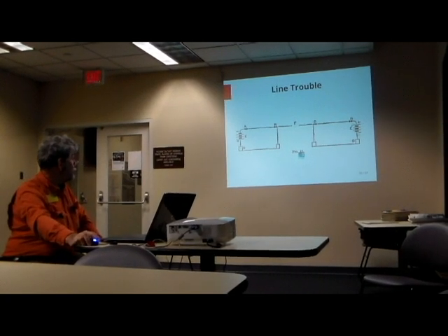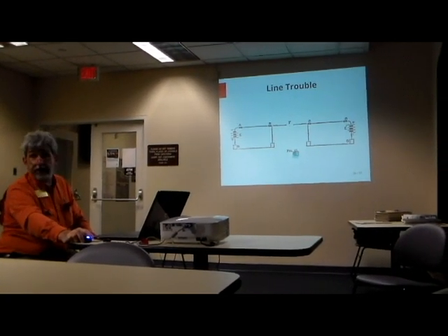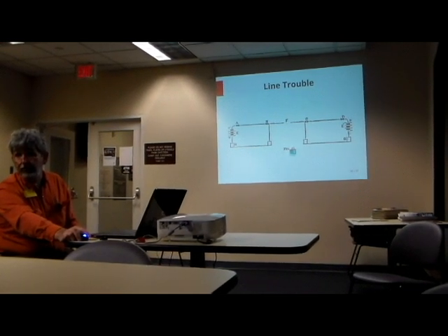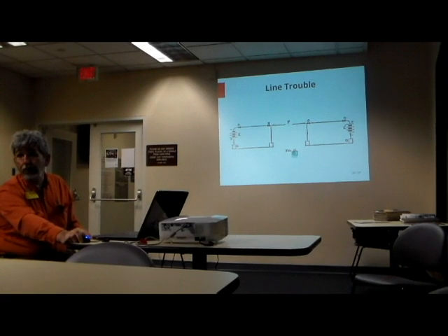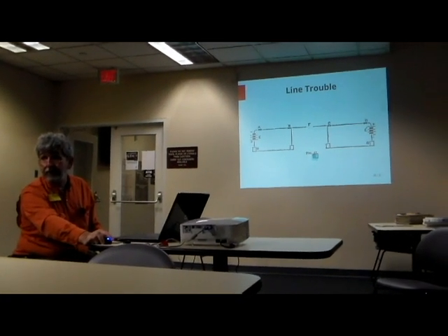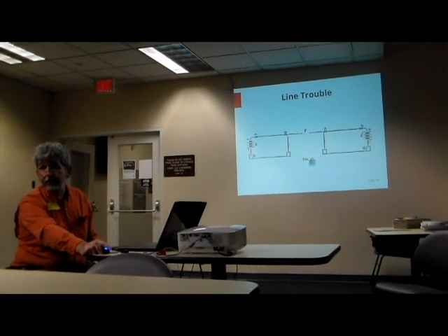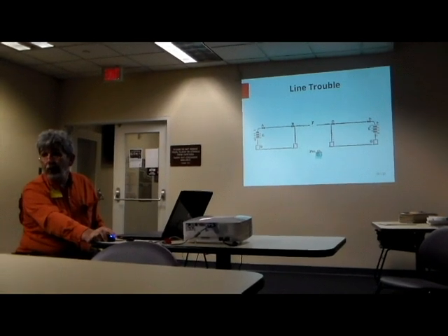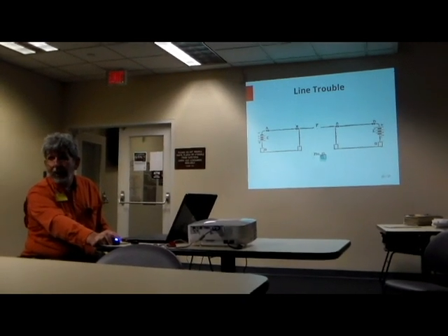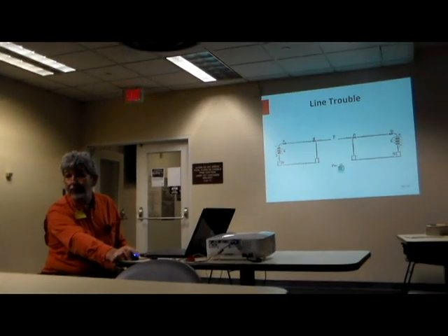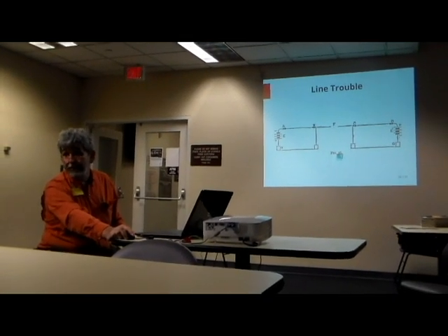But notice the batteries. Pretty quickly, the normal practice was to have a battery at each end of the line in the terminus stations. One down, one up. What do I mean by that? At one end, you ground the positive. At the other end, you ground the negative. And between the two batteries, they make enough voltage to overcome the circuit and coil resistances in the line. Why that's a good thing is when the line breaks, you still have a battery at each end and ground return to make a complete circuit.